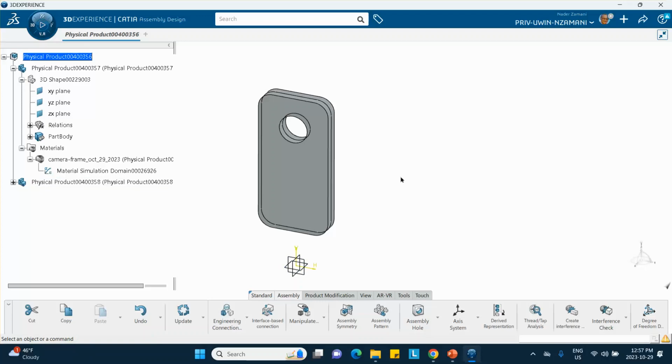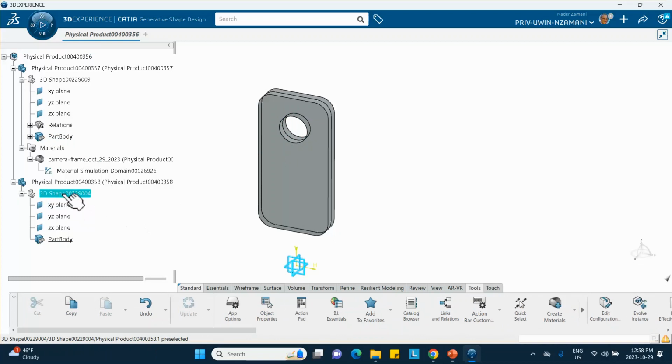Now we can create the lens right where it is, or I can create it somewhere else and then move it here and assemble it. Okay, the choice is yours. I'll make it right there. So on that, let's go to the part 3D shape. On that plane, what is that, YZ plane? Is this right? YZ plane. We'll sketch.